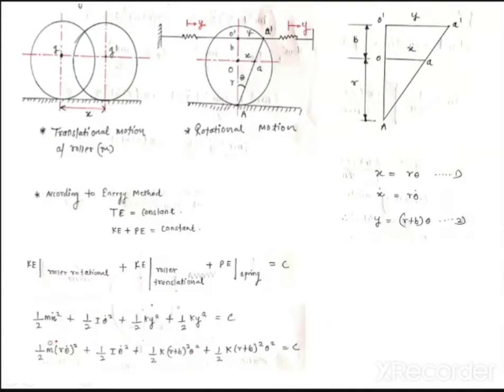Now, anybody tell me what will be the I for this roller having mass small m? This is point P. You have to use I at point P or I at point O. Last time I have already calculated. Which do you have to use in this problem, IP or IO? IP, yes. So what is IP? We already calculated IP, no need to calculate again. What is IP? 3 m r square by 2, right?